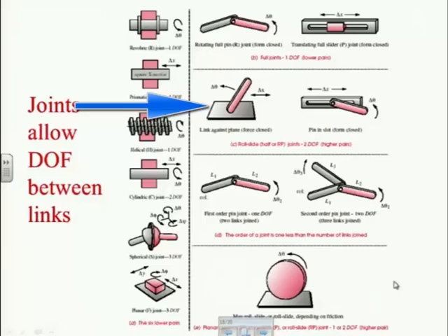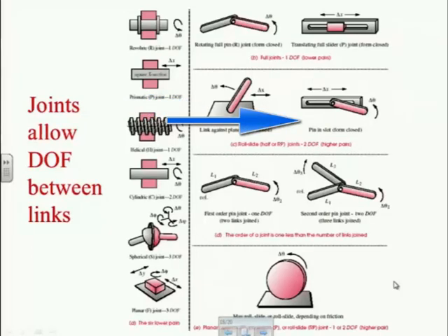So I have to have a force, which could be gravity or it could be a spring or something on my hand, holding it together to make the joint exist. If I put a pin in a slot, I now call that form closed by the geometry, because the pin is trapped in the slot, and thus I don't have to have a force to keep them together any longer, but I still have the 2 freedoms, because I can move that pin left and right along the slot, also rotate it about any point. So kinematically they're the same, but their constraint is different, and in one case I have to put a force on it, in the other case I don't.